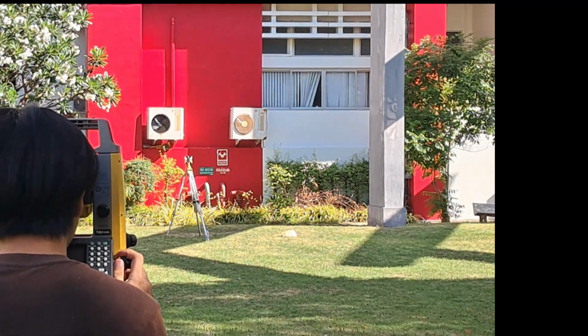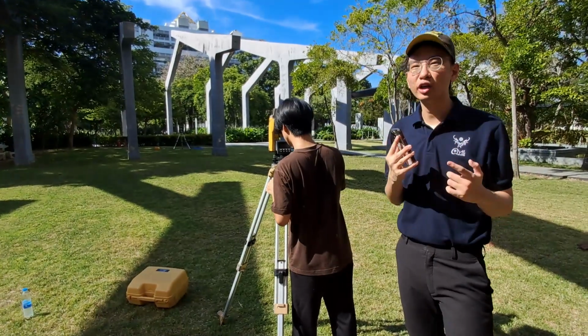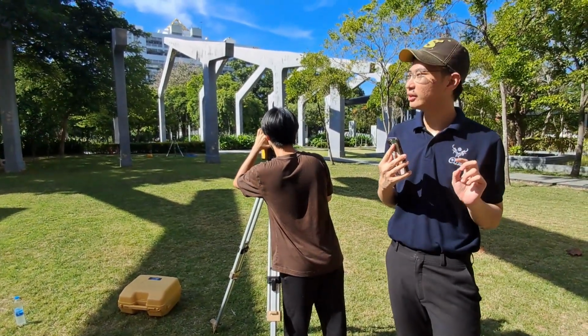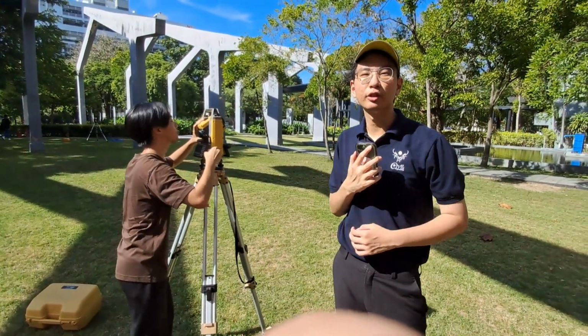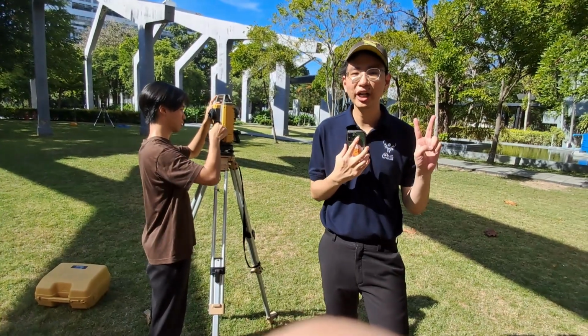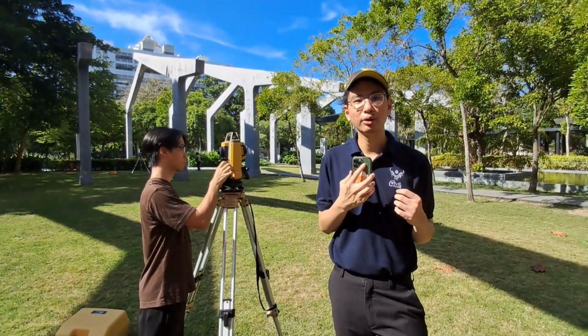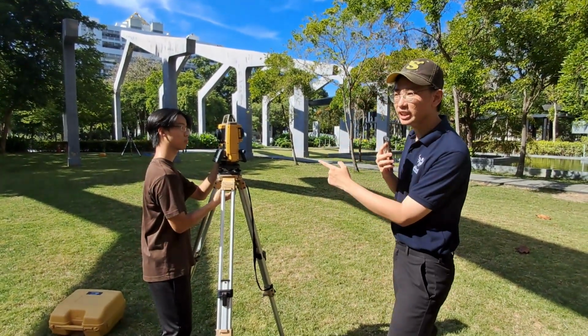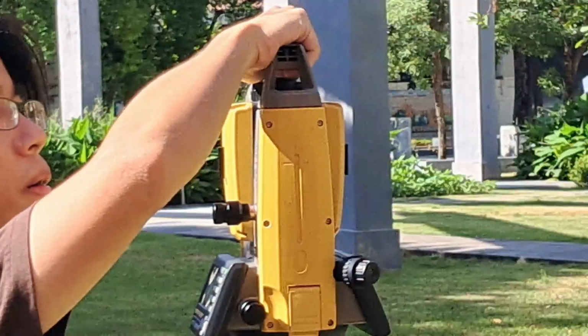For measurement of angles by this total station setup and the previous setup, we will use the direction method of 3 sets. So next we will continue with the second angle measurement, which is from the top of this building to the top of the other building that we want to know the distance of. This will be done by the direction angle measurement method, which is the same as the first one. And after we finish these 2 angle measurements on this total station setup and the precision of the reading is acceptable, we will switch the place between this total station and that prism setup so that the prism will be on this point and the total station will be on that point.